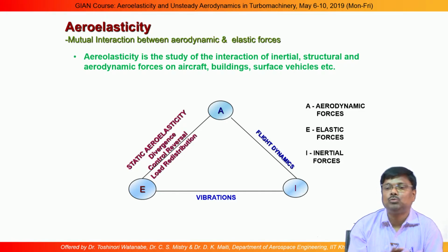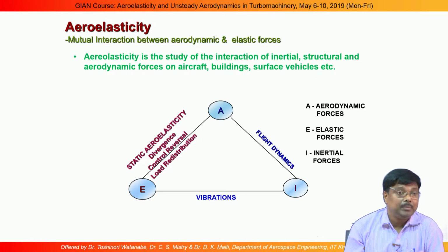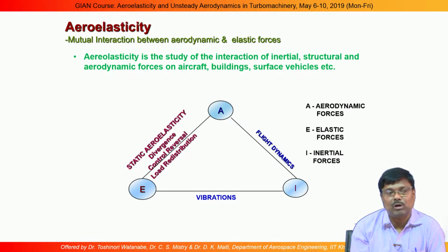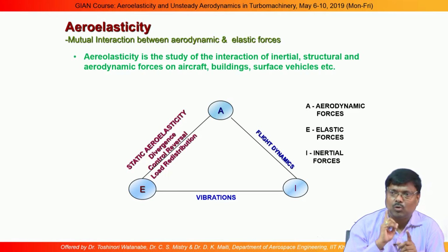Both forces cancel each other. Then we can have another effect, that is load redistribution, because in the beginning of the aircraft analysis, we usually consider the aerodynamic load to be a rigid load, and then we proceed with some design, because design is not a one-step, forward-only process, it is an iterative solution.